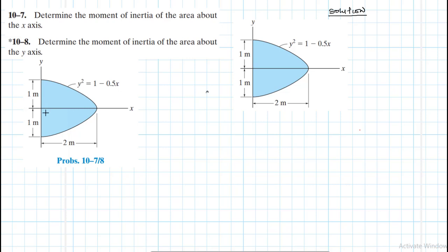If we are taking moment of inertia about the x-axis, like I said in my previous video, we need to take a differential strip that is parallel to that axis of interest. I'll take a strip like so, because this makes the work easier, and we want the work to be easier always, right? So let's take a strip of thickness dy.